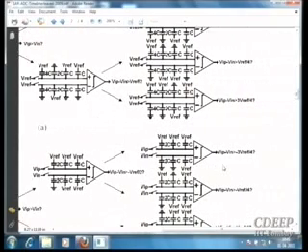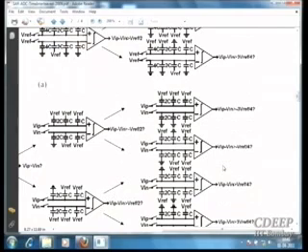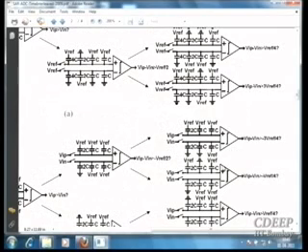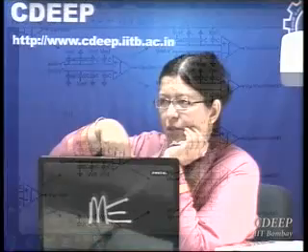What will happen here? Oh, maybe, because you are switching only one side. For example, if you want to generate Vref by 2. Actually, I think what happens is that, to generate Vref by 2 in the upper one, which is differential, you need to generate, for example, Vref by 4 and minus Vref by 4, or 3 Vref by 4 and 1 Vref by 4.